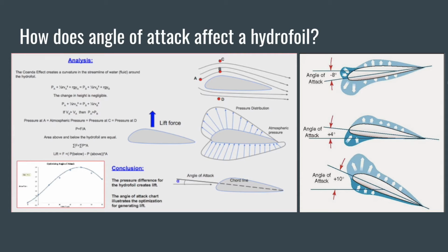As an object moves through the air, molecules stick to the surface. This creates a layer of air near the surface called a boundary layer that in effect changes the shape of the object. The flow turning reacts to the edge of the boundary layer just as it would to the physical surface of the object. To make things more confusing, the boundary layer may lift off or separate from the body and create an effective shape much different than the physical shape. The separation of the boundary layer explains why aircraft wings will abruptly lose lift at high angles to the flow. This condition is called a wing stall.